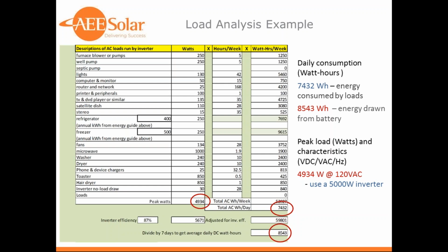So yeah, with about a 5 kilowatt load, we really want to use a 5 kilowatt inverter. It's certainly possible for the owner to load manage and not run too many things at the same time. A 4 kilowatt inverter would probably work fine in this application, but that really depends on the customer.